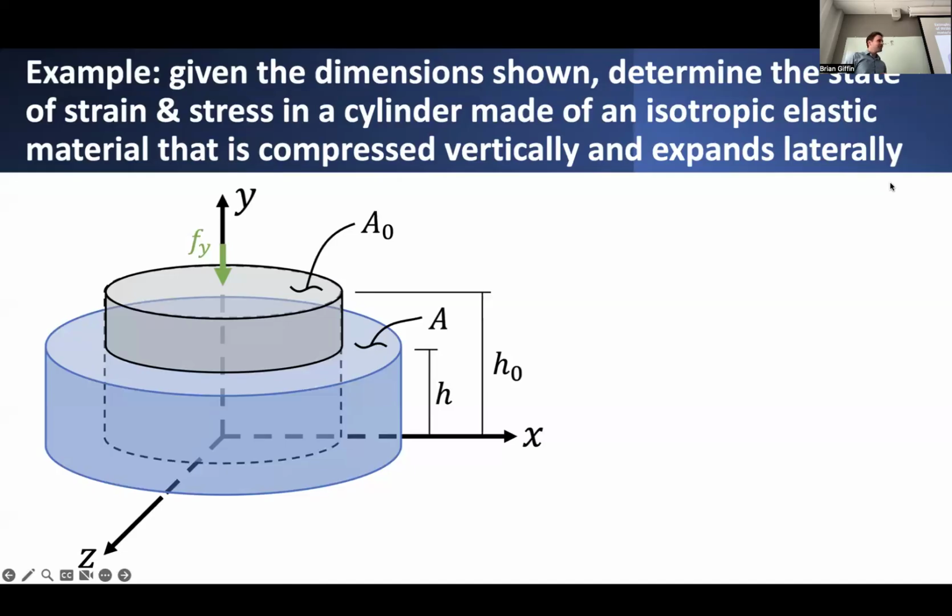That would be one valid way to determine the longitudinal strain in these transverse directions from the loading. Or we could make some approximations and say, let's assume that this cylinder is going to deform in a fashion which is basically axisymmetric. So the longitudinal strain in any direction within the XZ plane, let's just assume it's going to be the same. It's not going to preferentially deform laterally in any one of these directions.